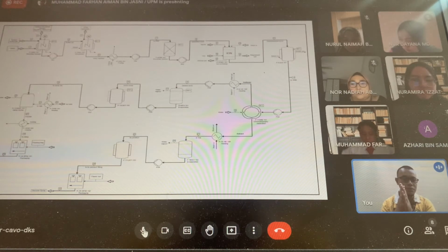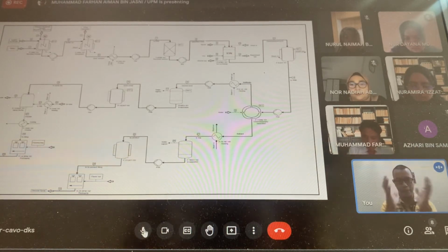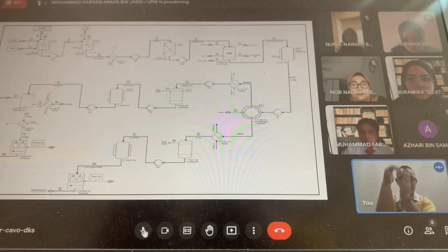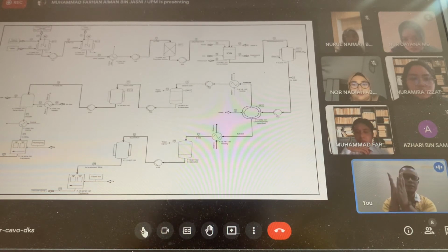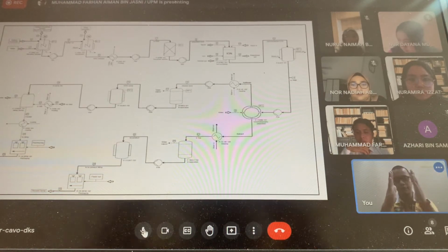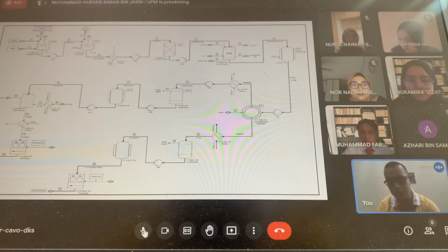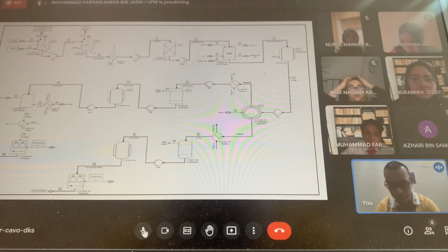When the last process goes to before going to the bag or pouch, there is what we call a load cell to record the weight. Let's say you're filling the powder until it reaches this load cell. It has a sensor going to the PLC. Let's say you set the set point at 10 kg. When it reaches 10 kg, they open the valve and dump it inside the bag or pouch. Based on the drawing I saw, it's not there, so make sure next time you put in the instrument. This is an important thing, where you have to control the weight of the product. Okay, the rest so far I see everything you have, right?